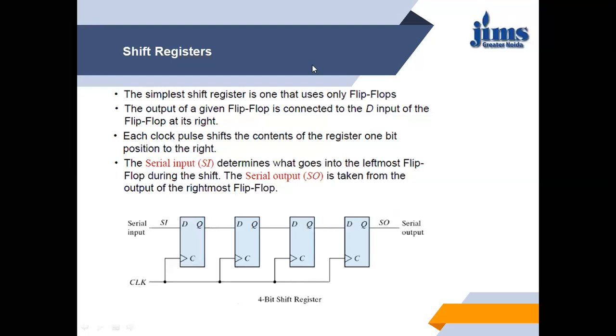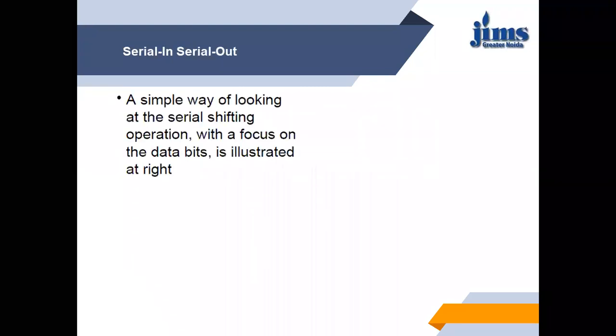Here is the common clock. So the output of a given flip-flop is connected to the D input of the next flip-flop. That is the simplest connection, and this is the simplest shift register, serial in, serial out. I have written here 4-bit shift register because I am using 4 flip-flops. Each flip-flop will store a single bit.